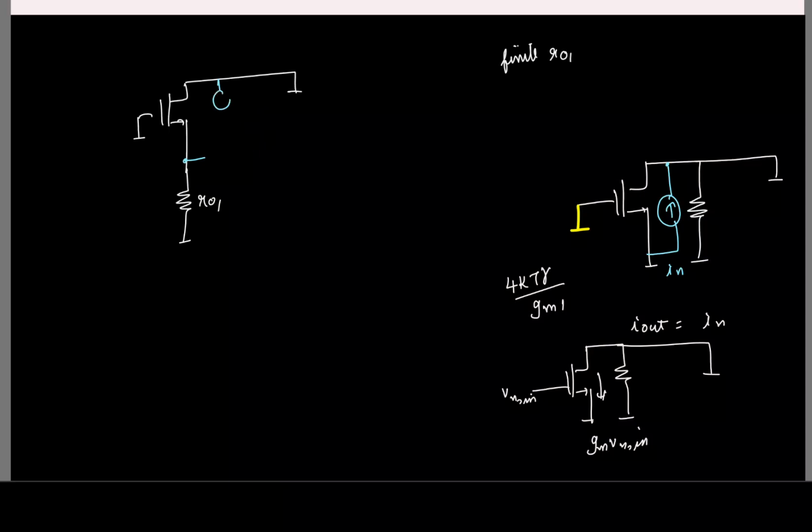Let us say this is one current source. Make sure that the directions are correct. If this is pointing down, this should also point down. That's the crucial thing. Say this is IN2, IN2. What do you think the contribution due to this one to I out is? Minus IN2. So I out will be minus IN2.